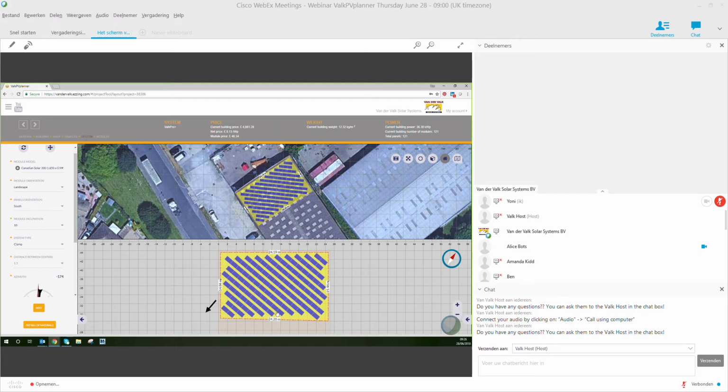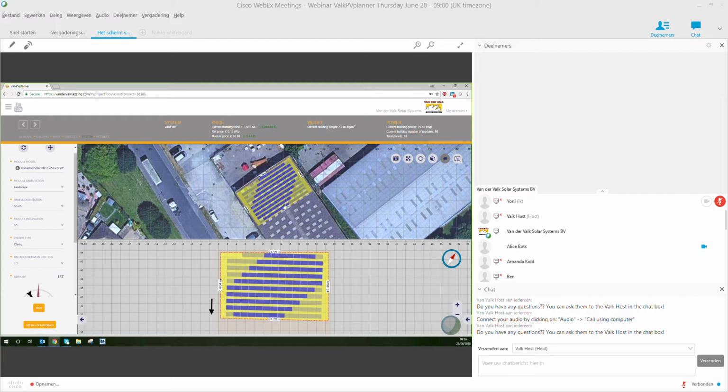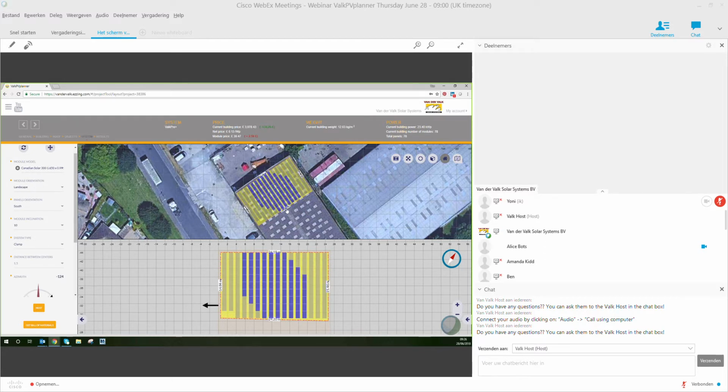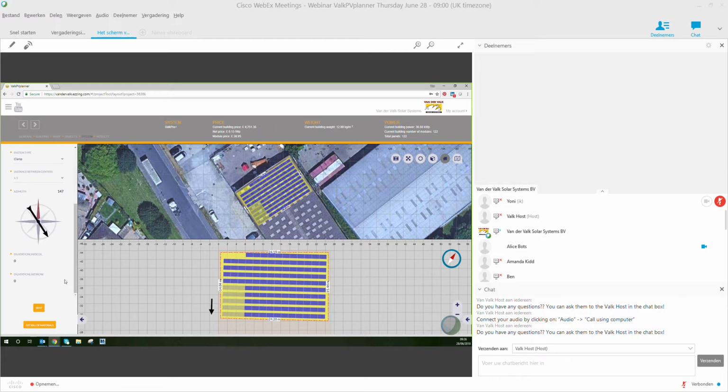Option 2, if you zoom in a little bit and select one of the axes, so for example this one, set azimuth perpendicular. That will then realign our panels perpendicular to this axis or this one, however you want to do that. And again, you can then fill that roof space and remove the panels as you need them. Obviously, ideally, once you get up to grips with the tool, you do all this first before you start to remove your panels and really finalize your layout.